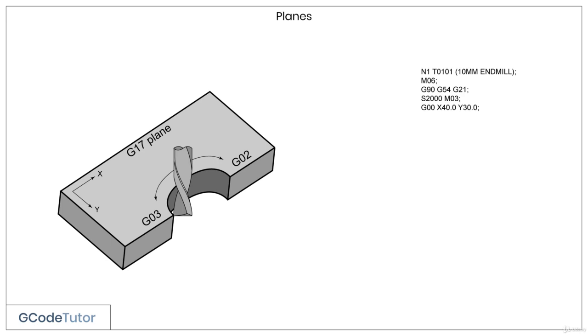And we now move our cutter into position using the rapid command of G00. G43 turns on our tool length compensation, Z10 brings the cutter down to 10mm off the face of the material, and M08 turns on our coolant. Using a G01 feed rate command, we now bring our Z down 30mm past the face of the material with a feed rate of 50mm per minute.